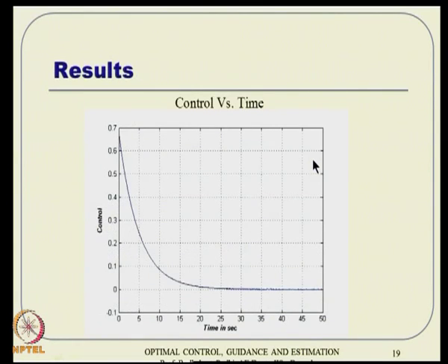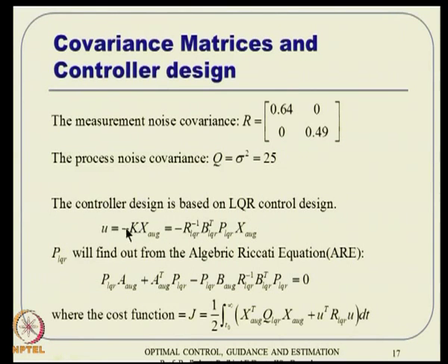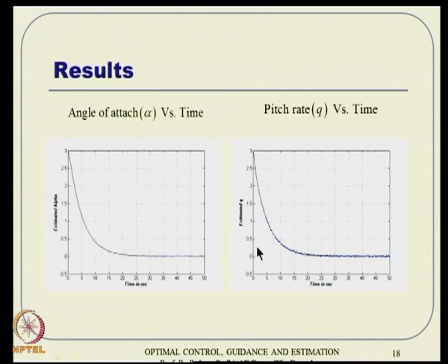Now, the whole idea is, can you modify the gain computation K and also the filter Kalman gain Ke? That was the core point. If you blindly select these numbers, like diagonal ones, and work with some time domain phenomenon like that, then robustness considerations are ignored. So, we have to go to the frequency response characteristics, and from there propose a design, a kind of tuning basket. You cannot tune wherever you want, but it gives you a basket from which you can pick your tuning values.